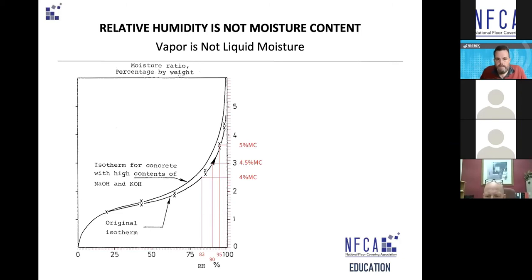So the way to understand this, and it's important that it's understood correctly, because this is intended to show you that the condition of the moisture is okay. In other words, if you take this bottom line of this chart, that is concrete that has hydrated properly. It has cured effectively. And so there is less salts present because they have hydrated, they have become concrete. So this is what we're hoping for. This bottom line is what we're hoping for. And that's why we've lined these up.